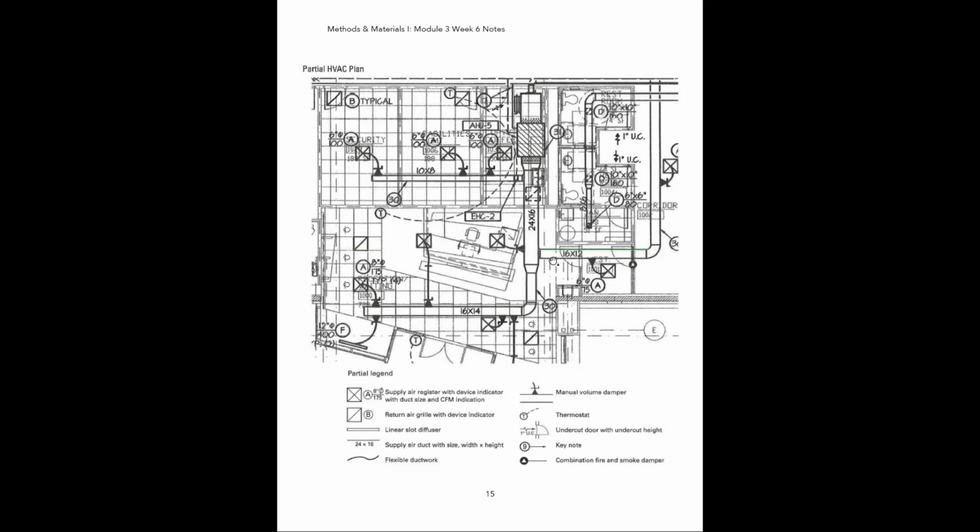So if you remember back to when I explained this, when we have a duct that's penetrating through a fire-rated wall assembly, like we're seeing here, I'm assuming this looks like it's a curtain panel system indicated by these three lines. So it looks like there's a mullion and then a pane of glass. I'm assuming directly above that curtain panel, there's going to be a gypsum wallboard wall that has some sort of a fire rating associated with it.